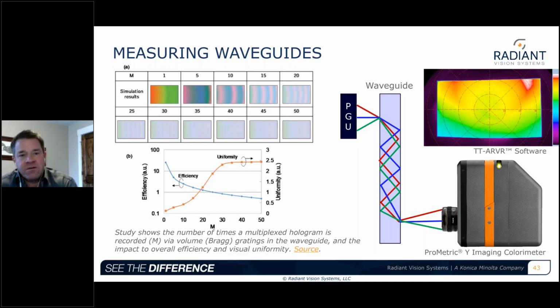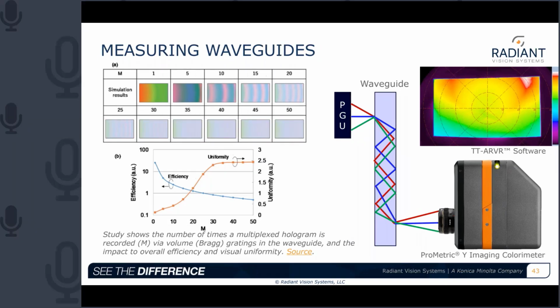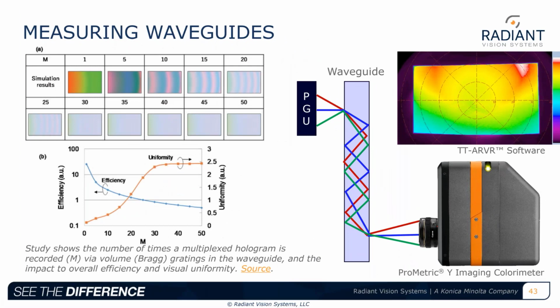Brightness, color, uniformity, and sharpness should be evaluated using a colorimetric imaging system to obtain absolute values to guide the optical design. These values include luminance and chromaticity and how they change across the image to determine uniformity, as shown in the upper right image. Because measurement data is quantifiable, numerical values can be used to compare results based on different structural changes to the waveguide.